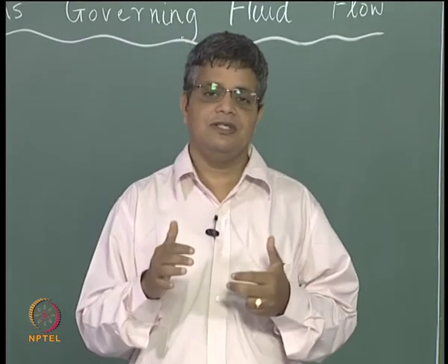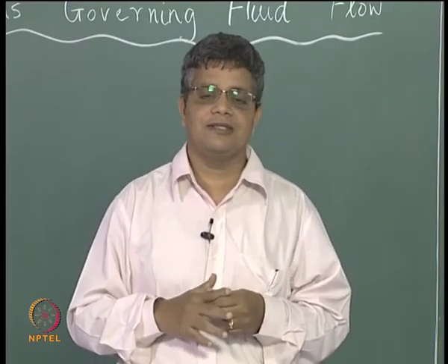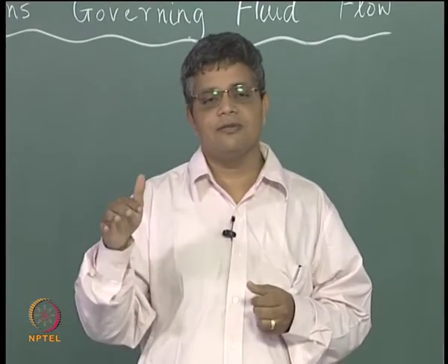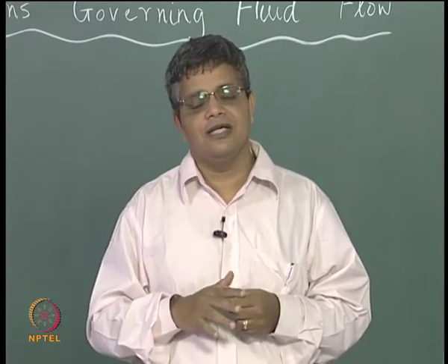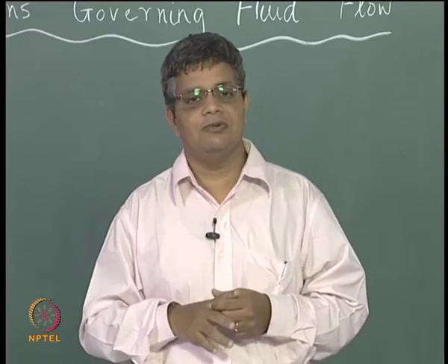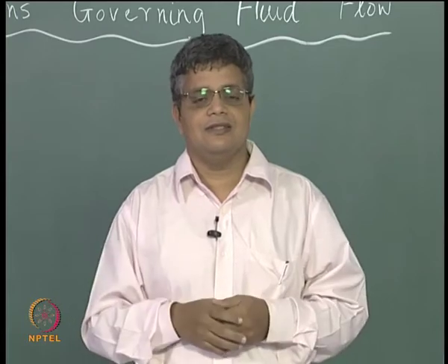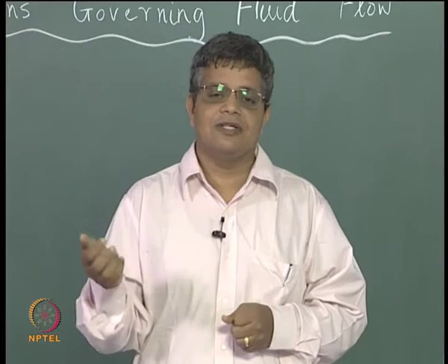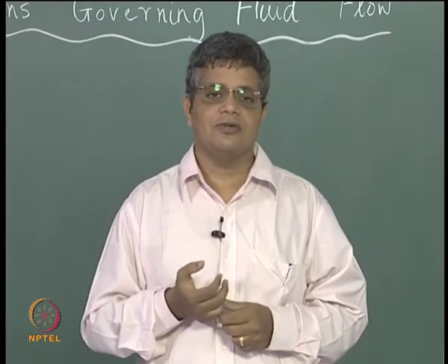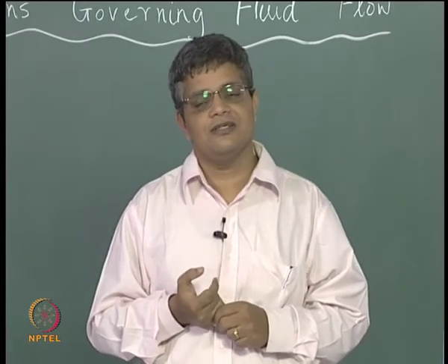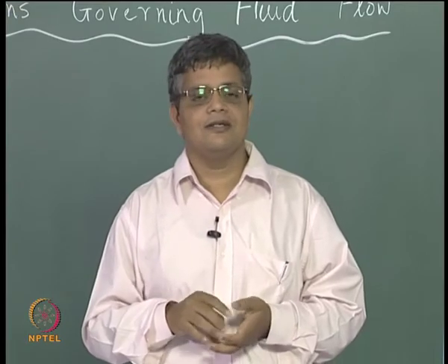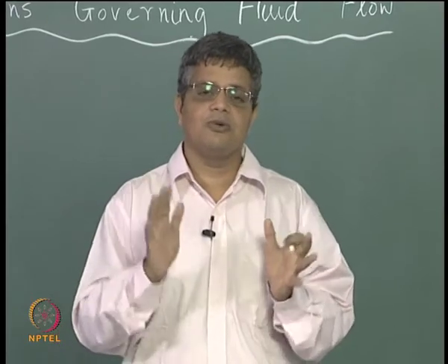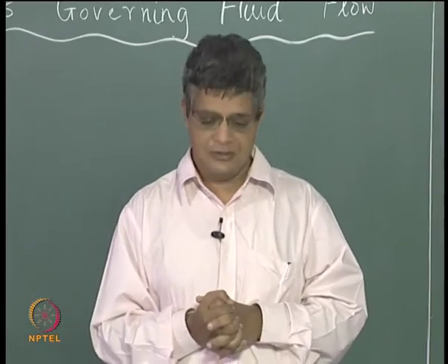So, we distinguish this in the fluid mechanics community as a Lagrangian viewpoint versus Eulerian viewpoint. Lagrangian viewpoint typically refers to the system related equations like what we have in solid mechanics. The rate of change of momentum is equal to sum of all forces acting on the system of particles, whereas in an Eulerian approach, we are looking at a control volume based derivation of the equations.